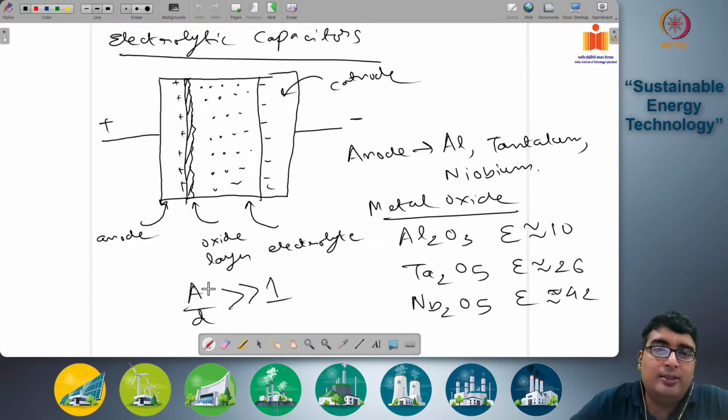We also saw that the rest of the distance between the cathodic plate and the dielectric metal oxide is filled up by some electrolyte which is able to transmit the negative charges to the surface of the dielectric oxide material. And this electrolyte can be a liquid, can be gel, or can be a solid which can create polymeric bonds with the metal surface to ensure good contact.